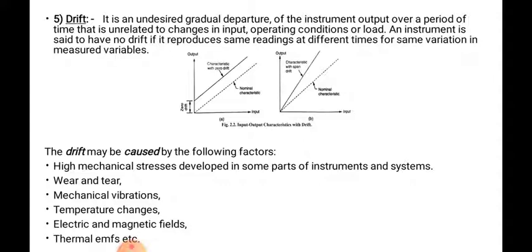Now what will happen? Suppose the digital odometer is showing 65 km per hour, then in that case the analog display meter pointer will show somewhat 62 or 63, or it may show a lesser reading, or some greater reading. So depending upon the effect of the drift, it will show a different reading. Most of you have observed whatever example I have given to you. So that is nothing but the drift.